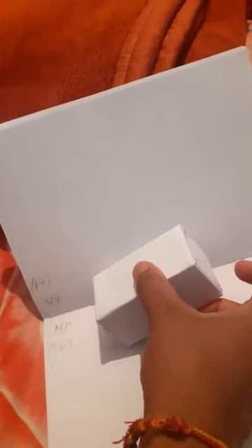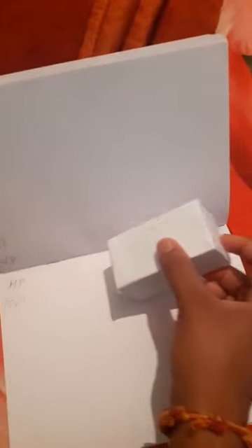two rectangular faces. In the third position, the axis is inclined to VP at 30 degrees. Now your axis is already inclined to the HP. When you view from the top view, you can see the reduced axis length. Already it is inclined. Then again you go for the third position, the axis to VP at how much? 30 degrees. Now rotate this.